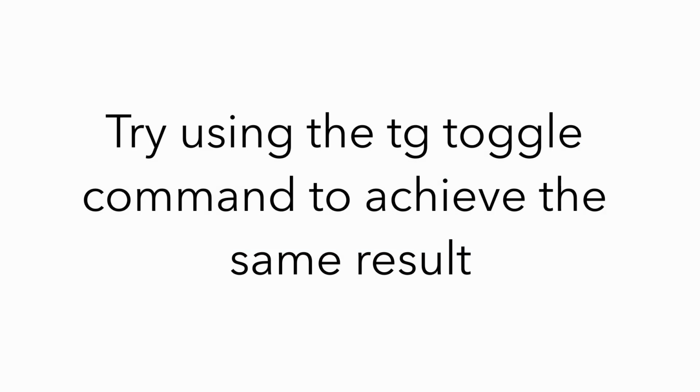In this example, we're going to use a series of daisy chain commands to flash the user LED on and off. Type the commands as shown into your JackBord and press Enter. If all is well, the user LED should flash on and off. Notice we have the user LED commands spaced with D250 delay commands. The D250 commands result in a 250 millisecond or quarter of a second delay between each change in the user LED. As an additional exercise, try to replicate the effects of this command using the toggle command.